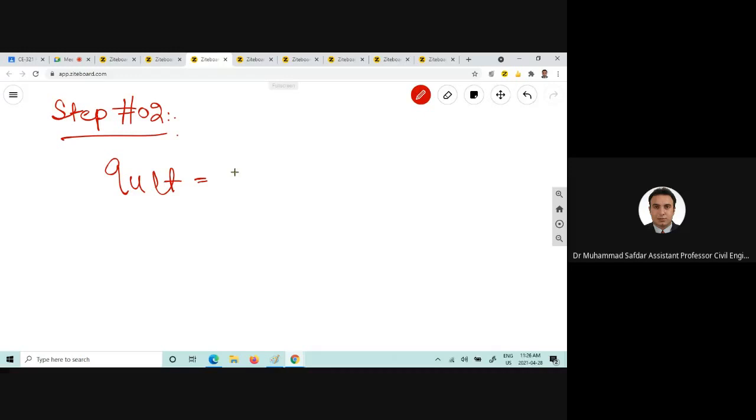Tell me Terzaghi's. Sir, Terzaghi's. So Qu is equal to C NC plus gamma D NQ plus 0.5 gamma B N gamma.